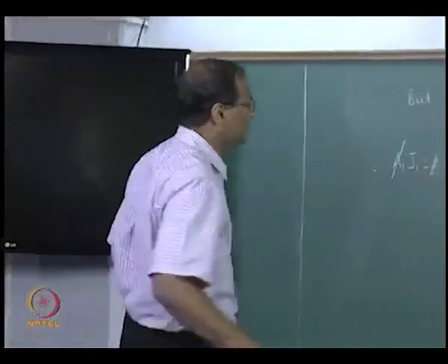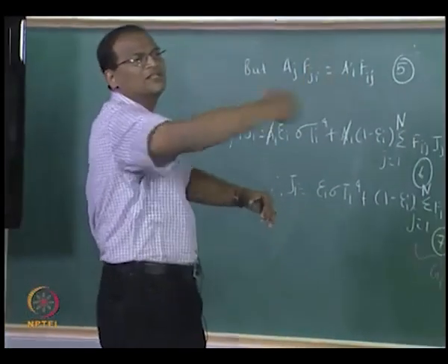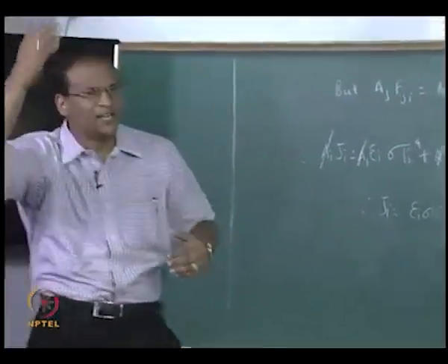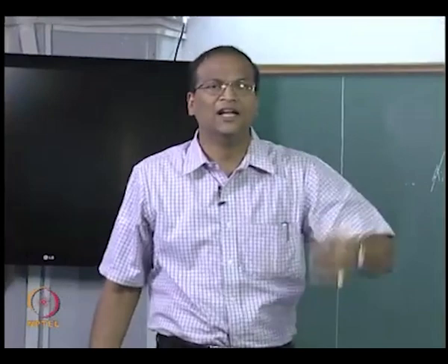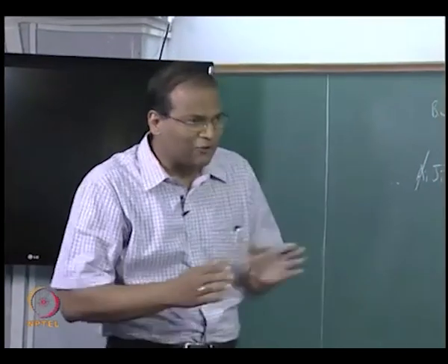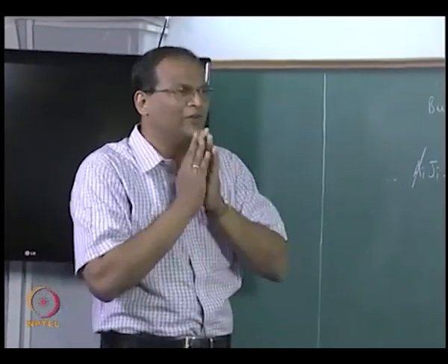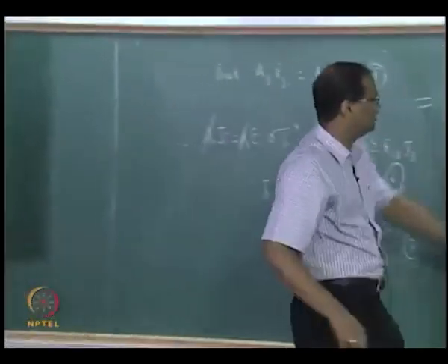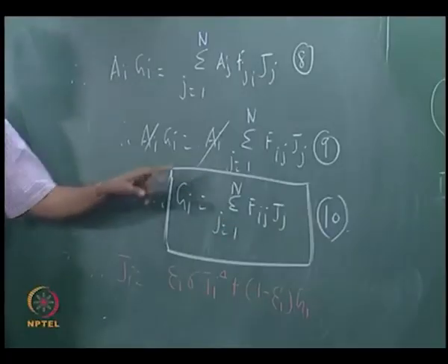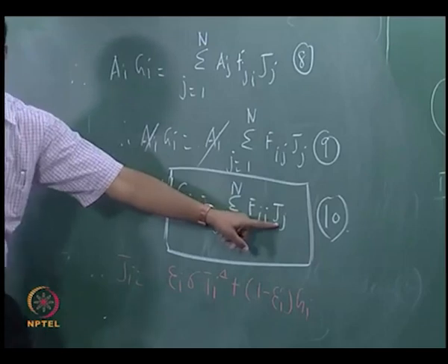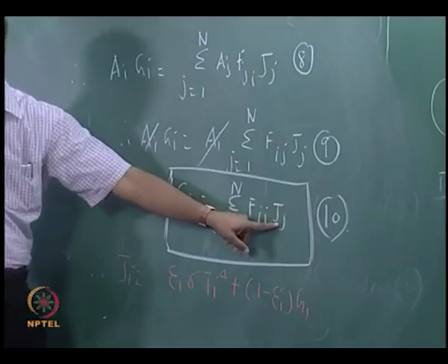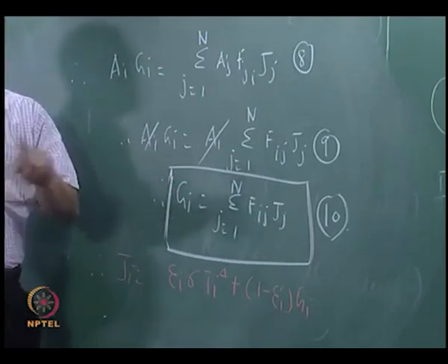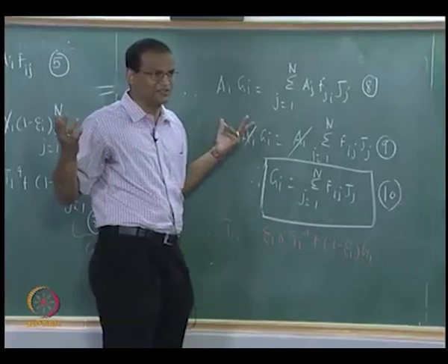Once you get all the radiosities, you can straight away use the formula for the net radiation heat transfer from any surface in terms of radiosity. Otherwise, if it is only 3 surfaces, if you have the time and the patience, you can individually evaluate G1, G2, G3 for all the surfaces from the J which you have obtained by simultaneously solving. Then get J minus G for 1, 2, 3 surfaces.